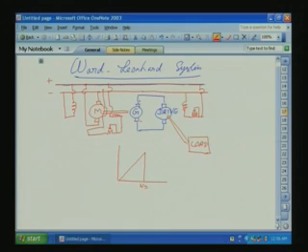Now, hereafter above base speed, what will we do? By controlling the field winding of the drive motor. Now, this drive motor field winding, we will slowly introduce the resistance, so that the excitation voltage will reduce and flux will reduce, and from here the system will go this way, inversely proportional to torque. So, we can have variable speed operation here. This way we will do it. So, speed control is possible here.